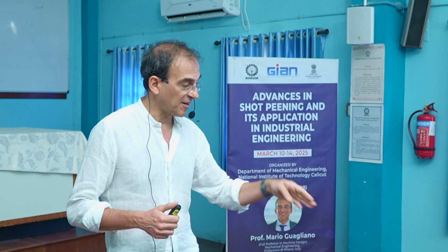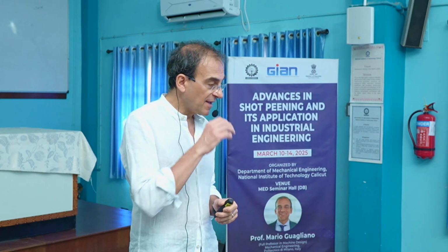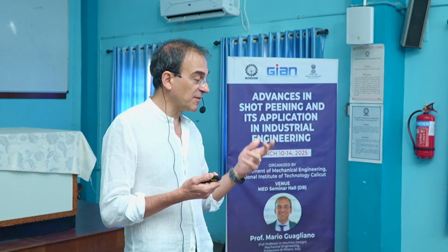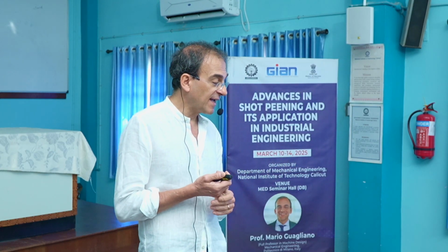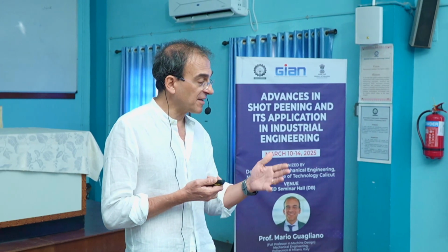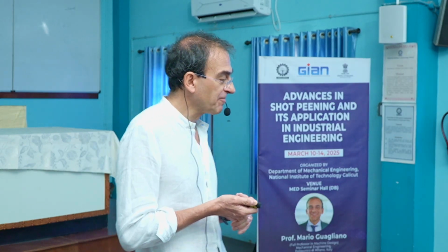So we have reached a maximum with severe shot peening, and by increasing the time we are damaging the surface. If we increase the treatment even more, the result will be even worse, of course. What is interesting is that with ascending, descending shot peening, AD-SSP, the fatigue strength result is the best. So by means of this novel way to apply shot peening, we are able to get the best result.